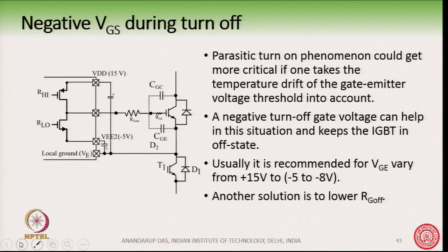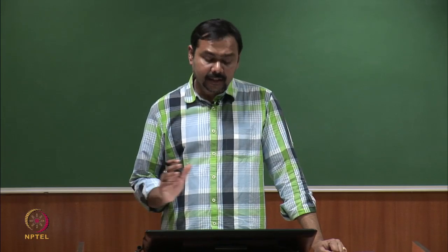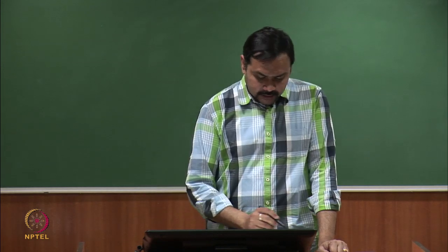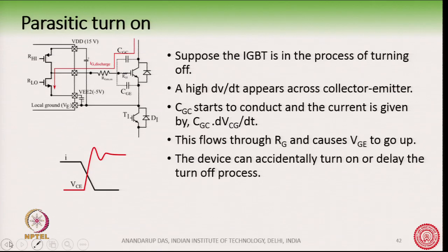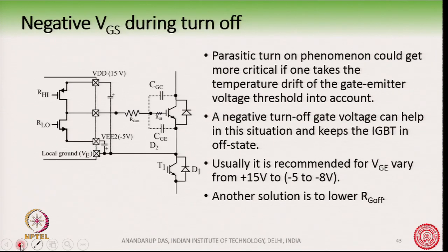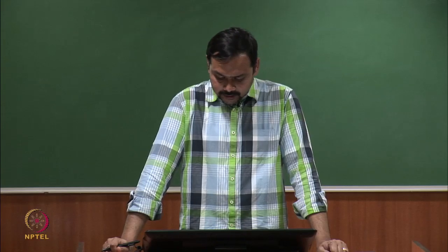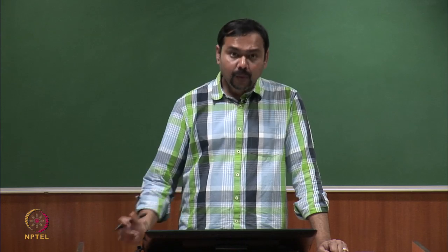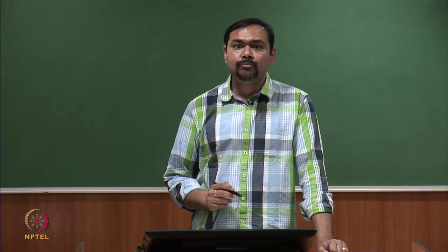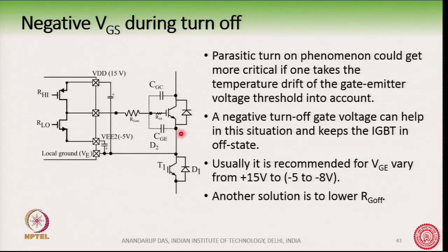Now you will appreciate why we had made VGS negative. So, another solution to take care of this parasitic turn on phenomena is to make VGS negative. Why? If you make VGS negative, that means this voltage, if you try to go into this one,